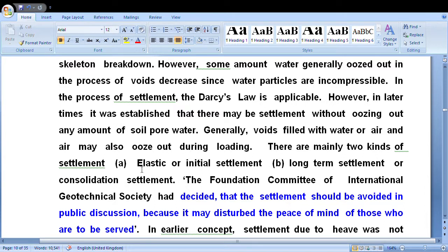Elastic settlement is due to the elastic modulus of soil. Immediate settlement is due to overloading. That means originally there is a surcharge, say about 1 ton at the foundation depth, and we added 15 tons, that is 16 tons overloaded, so there will be some particle rearrangement. Due to particle rearrangement, the immediate settlement will be there.